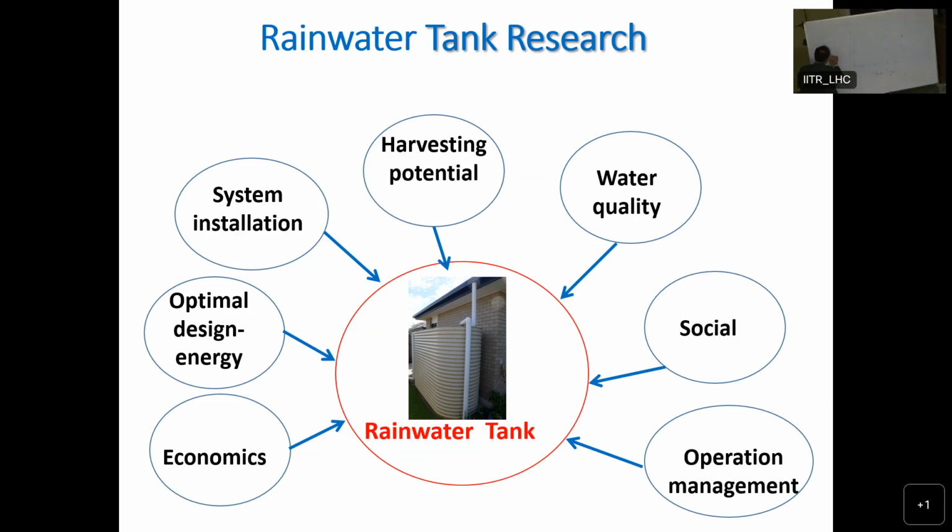So the other question which we're talking about, this is the tank size, and that is the volume that has been utilized. Maybe when we start with a 5 kiloliter tank, we may be getting that much volume available for application. When we have 10 kiloliters, we will have a curve like this in general. So this gives you basically volumetric reliability.